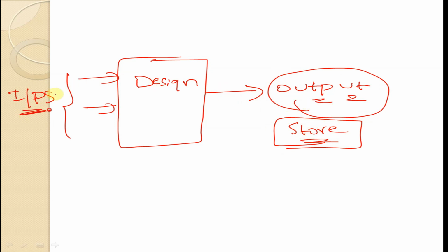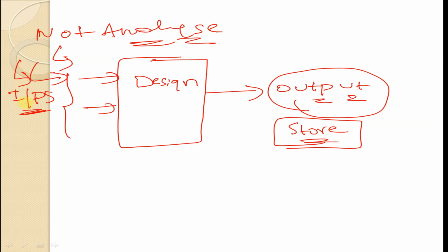But on the input side, we will not want to analyze any values because we are only driving the inputs. So the inputs are mainly of wire type only. In Verilog the inputs are wire type only. We will not store any value in the input ports, but in the output we will store the value for analyzing purposes.